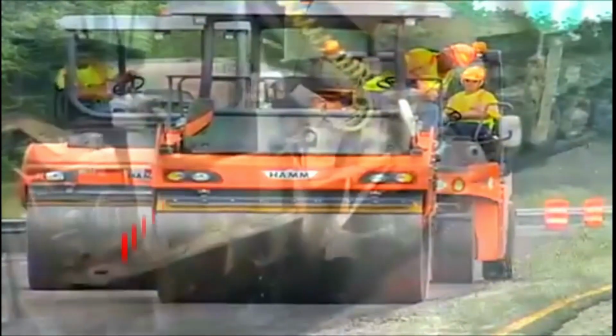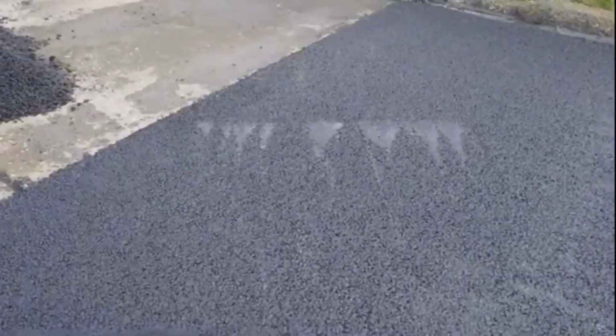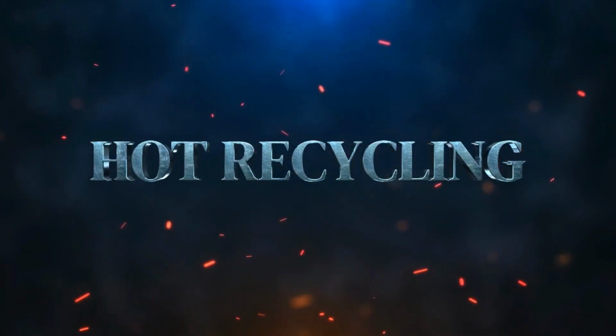Step 6. Final surface layer application. A thin asphalt layer or chip seal is applied over the recycled base. The road is open to traffic after proper curing. Hot recycling method. What is hot recycling in road rehabilitation?